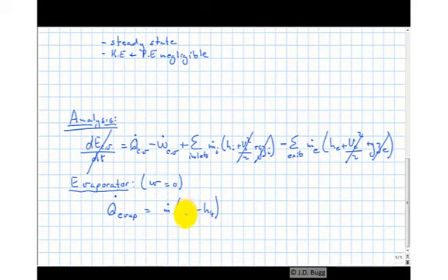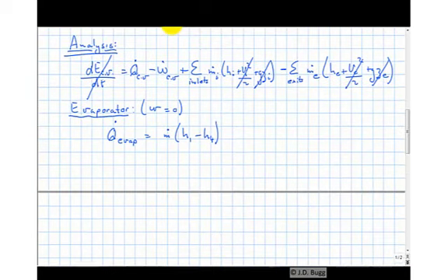So that's the simplified form of the energy equation for the evaporator. h1 we can get because we know pressure and temperature there. We'll do that in a moment. h4, we'll have to look at the throttling valve to get that. So let's get our h1 first. Well, at P1 equal to 1 bar, the first thing we do is look up the saturation temperature.